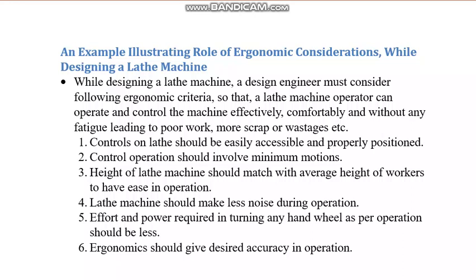So what will you consider? While designing a lathe machine, a designer must consider the following criteria so that the lathe machine operator can operate and control the machine effectively, comfortably, and without any fatigue. Otherwise, what will happen? Poor work and more scrap and wastages will result. Okay, what are the things? The first one is that controls on the lathe should be easily accessible and properly positioned.